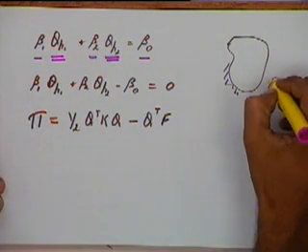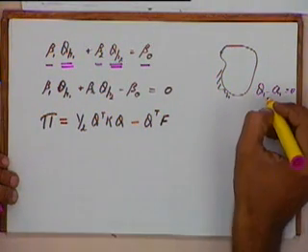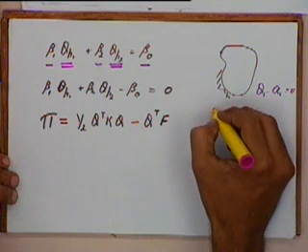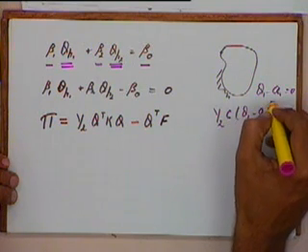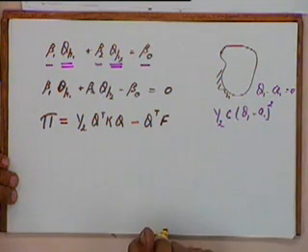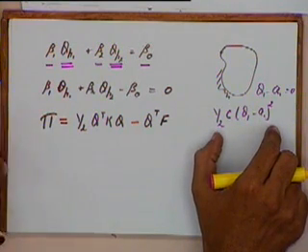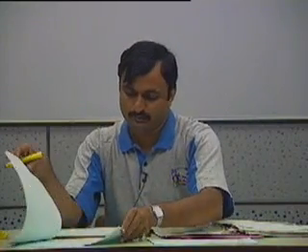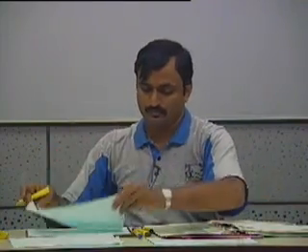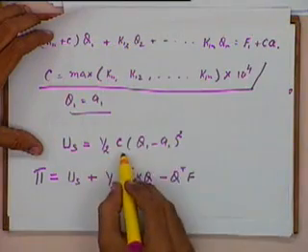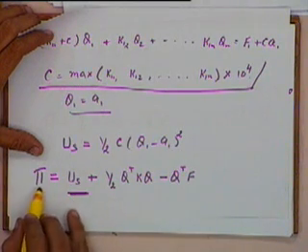Earlier we had a boundary condition of the type Q1 minus A1 equal to 0. So the penalty that we gave was of the type half of C times Q1 minus A1 whole squared. This is the penalty we had given to the potential energy. This is the potential energy of the spring, half of C into Q1 minus A1 whole squared, which is the penalty we had given to the potential energy expression.